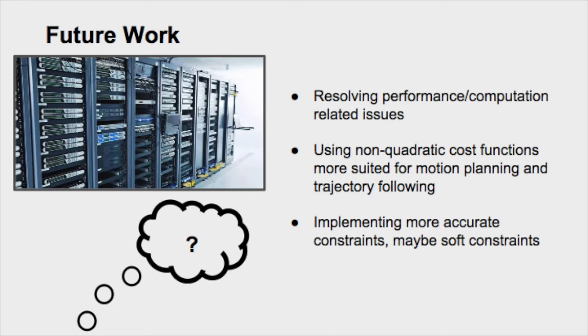Performance has been the limiting factor throughout our project, especially due to the fmincon solver. We managed to achieve a 5-time speed up by providing fmincon with analytical cost gradients, and providing analytical gradients for dynamics should improve performance further. We hoped to do this by evaluating the functions in the robotics toolbox using symbolic variables and differentiating the result. This idea did not work because the robotics toolbox only supports numerical computation. We then tried re-implementing the toolbox functions using symbolic variables. Our symbolic dynamics functions are mostly working, but we did not integrate them into the project due to time constraints.